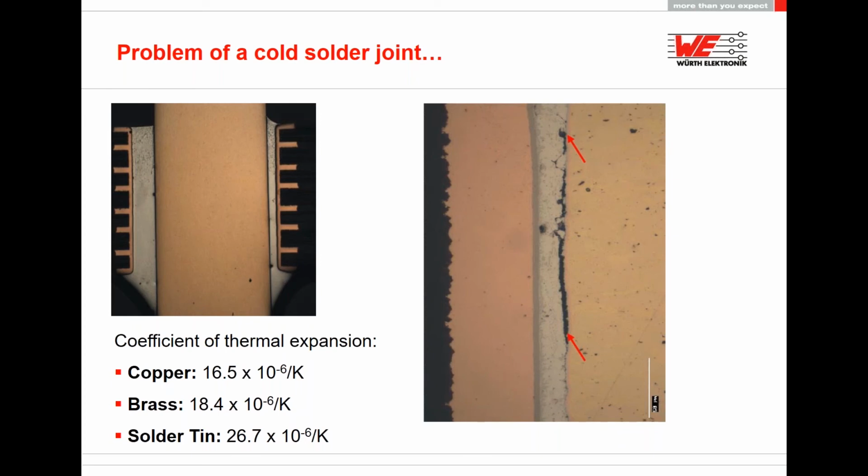And so it means all your current is coming to only the first layer. Additionally, you have solder in between. For the SMT component, you have solder here. And with the solder, as I told before, the solder has up to 10 times higher resistance than copper itself. So you have automatically higher resistance.